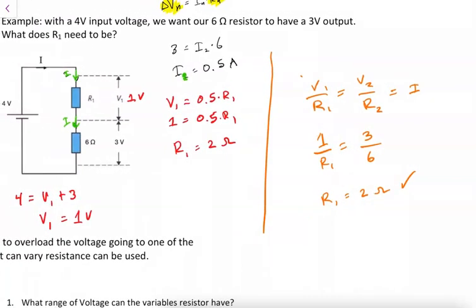Recognize that this particular way, when solving for resistances, only works in series because the voltage is proportional to resistance. In parallel, because the voltage is the same in each branch, this way doesn't work, but there is probably a similar way to solve for the currents, which are inversely proportional to the resistance.